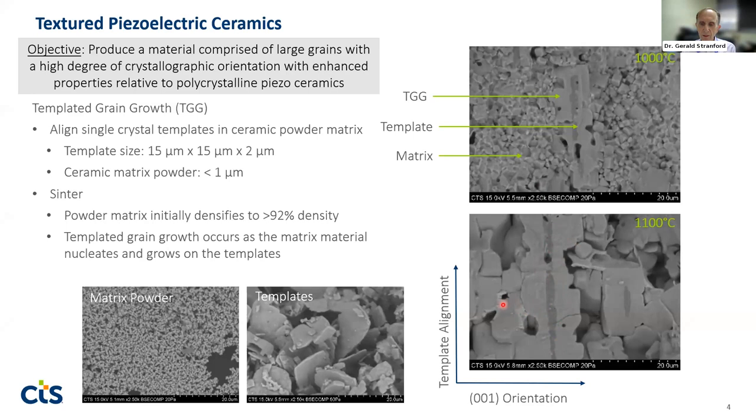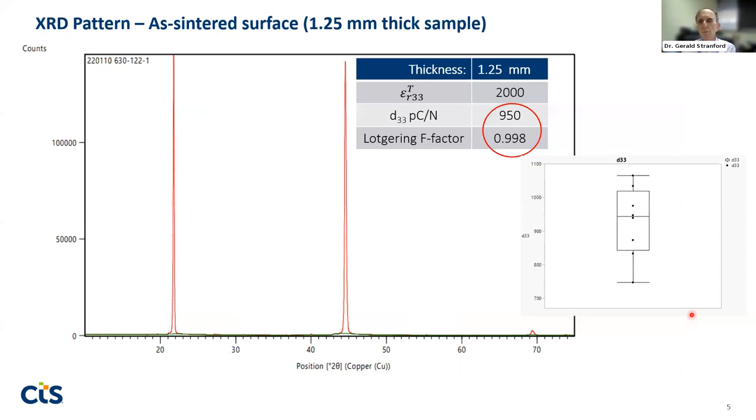There are some lighter areas here, which are residual liquid phase that of course has solidified after we cool down, but it's a lead oxide rich phase that's present in the microstructure. And I believe that's one of the things affecting our reproducibility and making the challenges we experience as we try to go to thicker cross sections.